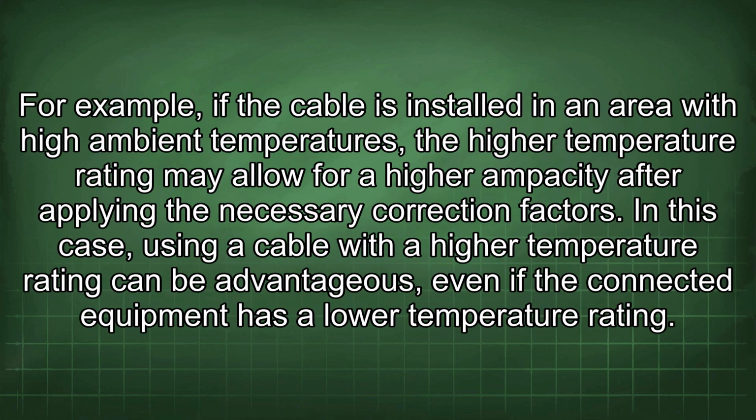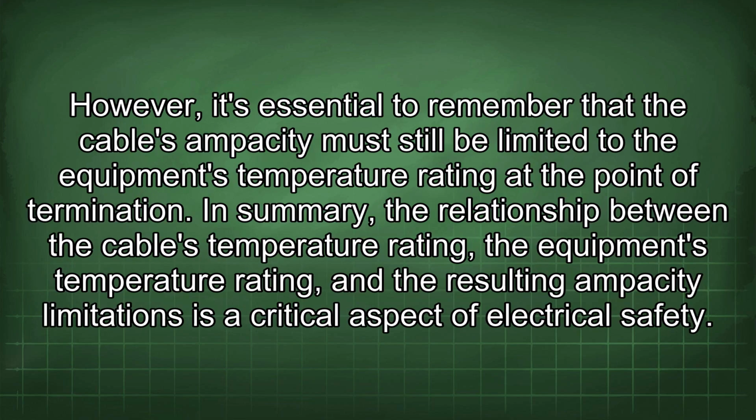For example, if the cable is installed in an area with high ambient temperatures, the higher temperature rating may allow for a higher ampacity after applying the necessary correction factors. In this case, using a cable with a higher temperature rating can be advantageous, even if the connected equipment has a lower temperature rating. However, it's essential to remember that the cable's ampacity must still be limited to the equipment's temperature rating at the point of termination.